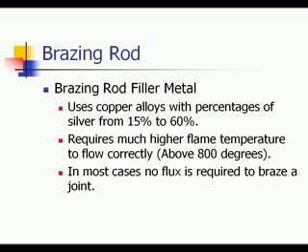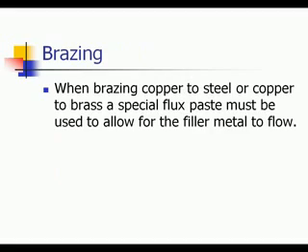So, with soldering, what you're doing is using your base metal. You have one pipe inside the other. You're using some filler metal called solder, and as you heat that base metal up, it pulls the solder into the joint, and when it cools, it creates a hard coating and joins the two metals together.